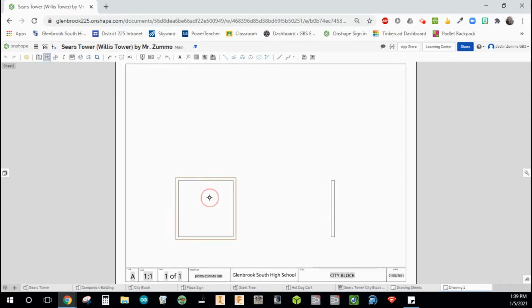So if I click on my front view again and drag up, there's my top view. And if I click on the front view one last time and go kitty corner diagonally, I'll get my isometric view. So a bunch of left clicking, projecting those views. Those are my 4 views I'm going to need. So now I'm going to hit escape on my keyboard. And that's going to cancel that projected view mode.